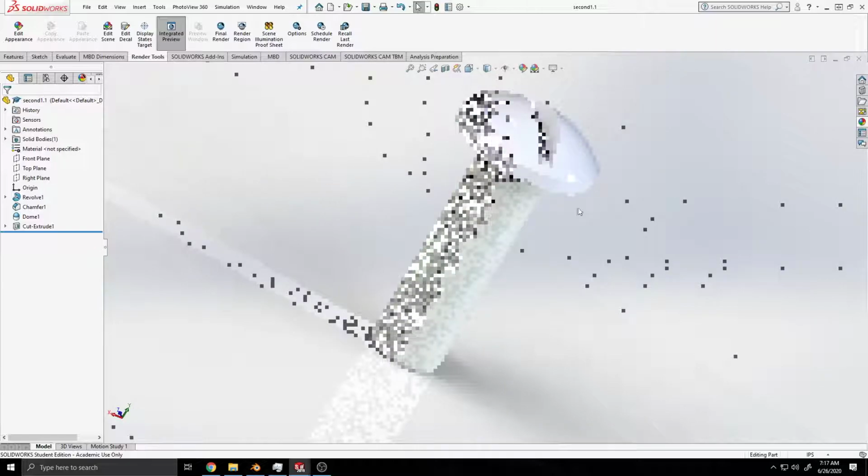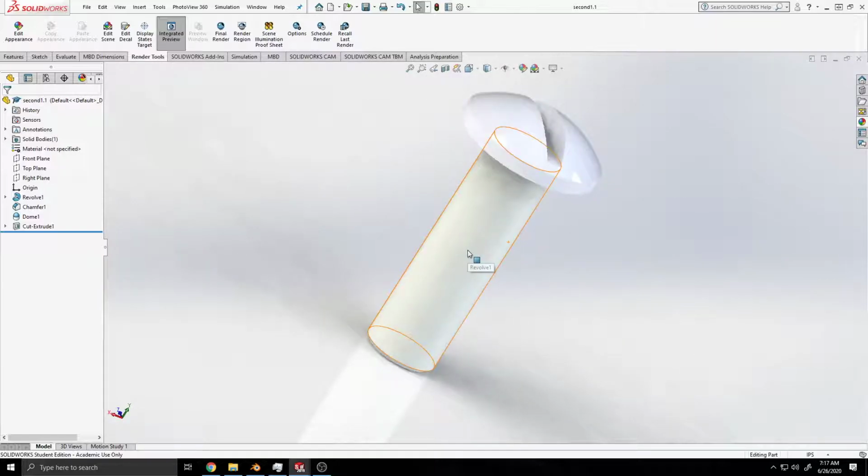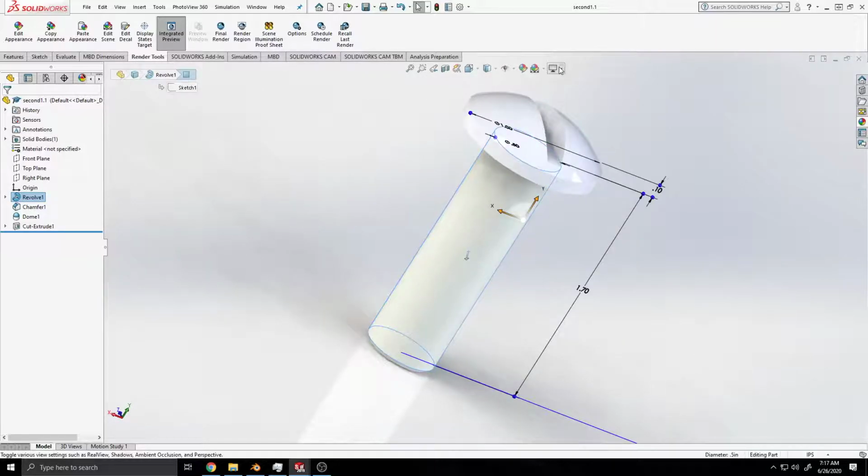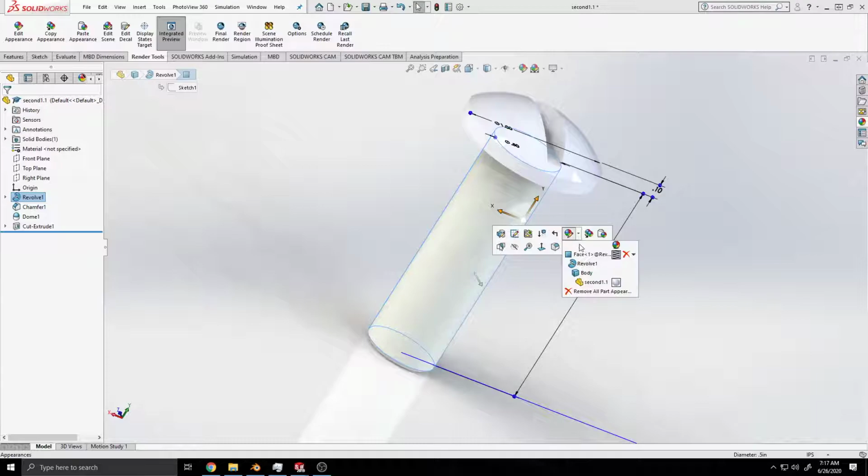I would recommend, so it looks just like what's in the picture, select the top plane and start a sketch. And then go to Center Rectangle, and at the origin, since it's symmetric, draw out your rectangle. And we know it's 3 by 6.